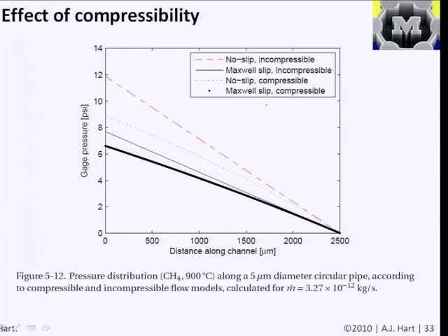So we could go through additional exercises that would let us derive the equations for compressible flow through these channels, and compressible no-slip flow and compressible slip flow. And basically, we won't go through it, but what you do here is, when we derive the volume flow rate, we were conserving volume flow and we weren't worried about density. And in the case of compressible flow, volume flow is not conserved. Like the volume going in can be different than the volume going out, but of course mass flow is conserved, so you just apply conservation of mass instead of conservation of volume, and you have a density gradient through the pipe, and that, with some more involved math, will let you solve for compressible flow in the channels.